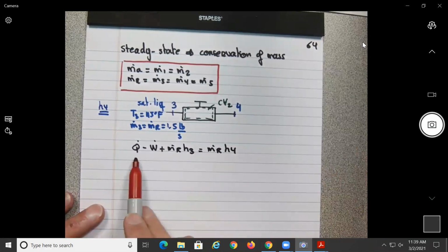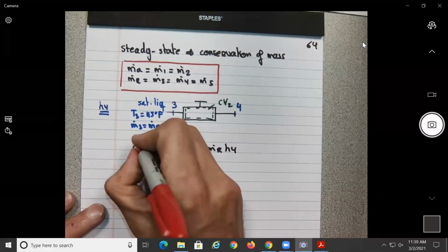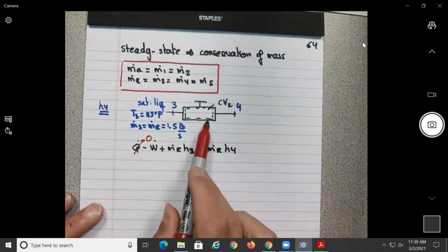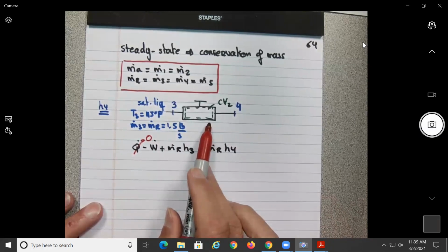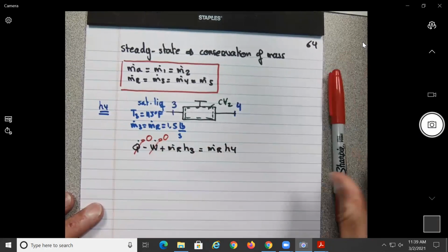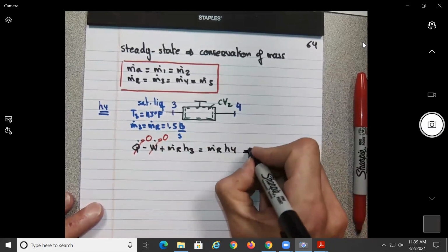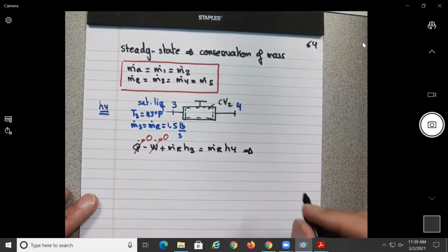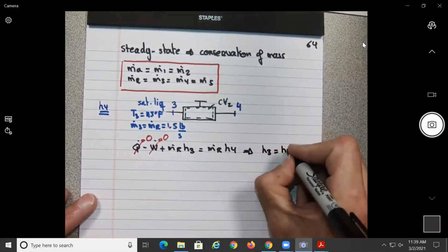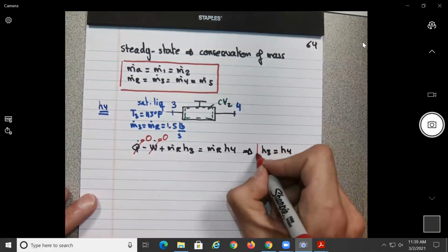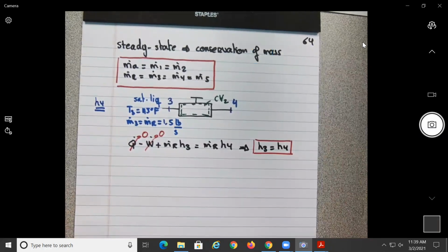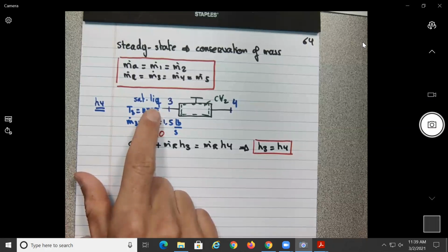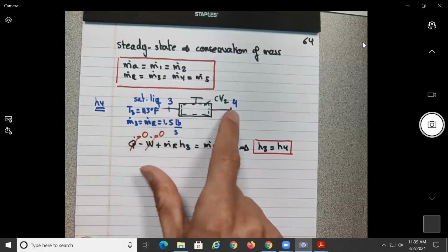Now, in this figure, is there any heat loss or gain by the valve? No, everything comes from the figure, no? If it's not on the figure, it's not happening. Is there any power that needs to be provided or given by the valve? No. So that means right away that when you go through a valve, the enthalpy is conserved. So if we find the enthalpy at the entrance of the valve, that should be the same as the enthalpy at the exit of the valve.